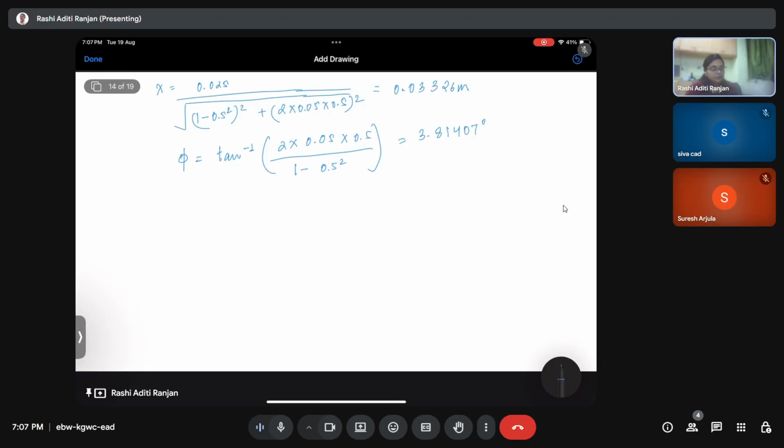Now, when we talk about the solution x of t, it is important to understand that for a system which has damping present, and when it has a certain initial condition, it is first going to show some transient vibration. At the end, since it has a forcing function, it is going to have a response with a frequency equal to the frequency of the forcing function.